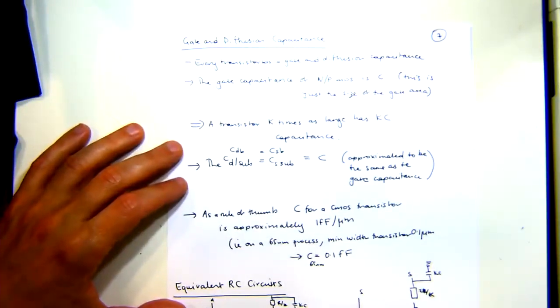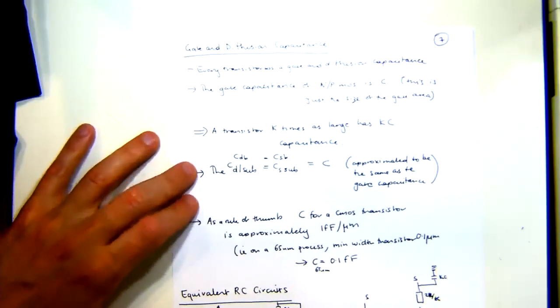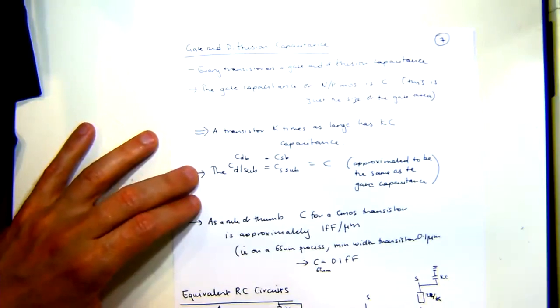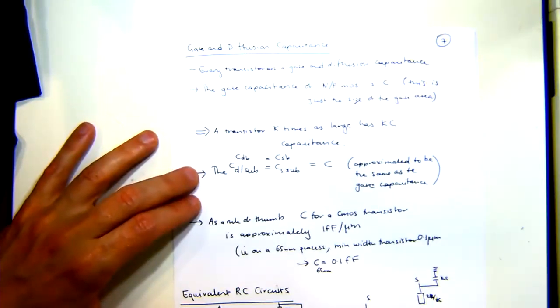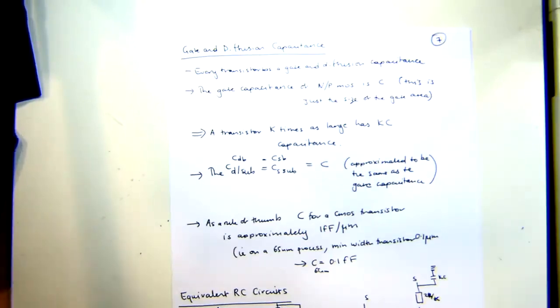But it's a good question. I like it. Usually what I'm trying to do is make everything linear, and that's what people do. Generally, you try to keep the minimum gate length and change the width of your device, rather than changing both the length and the width, because if you change the length, the device slows down. Transit frequency is 1 on the length of the gate.